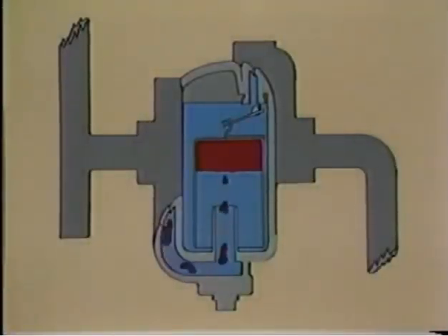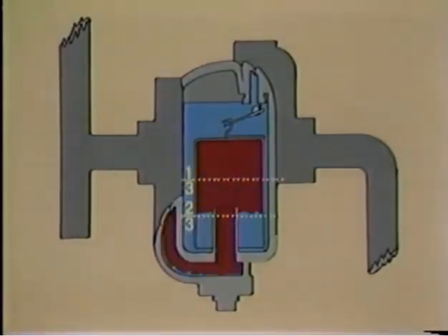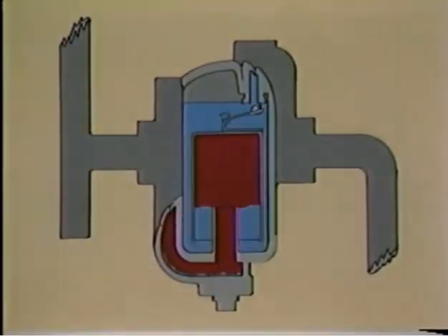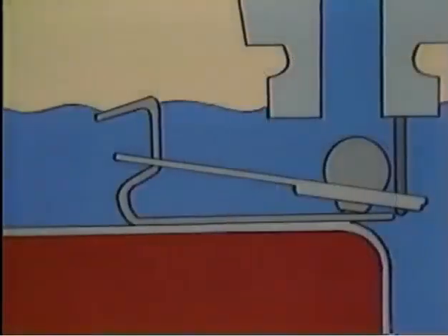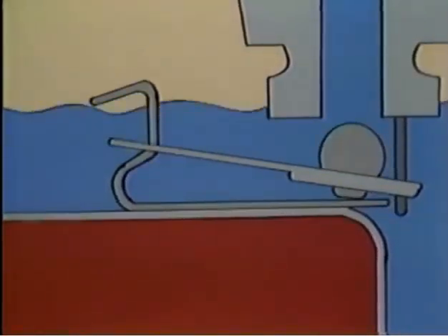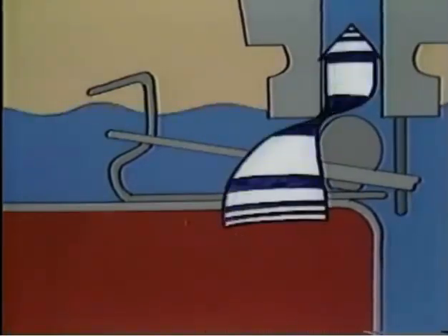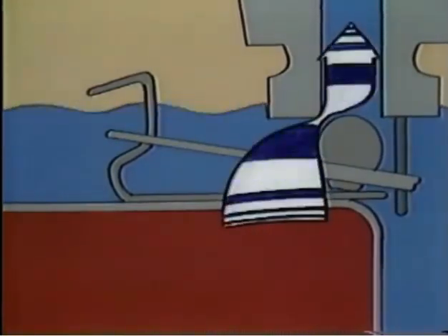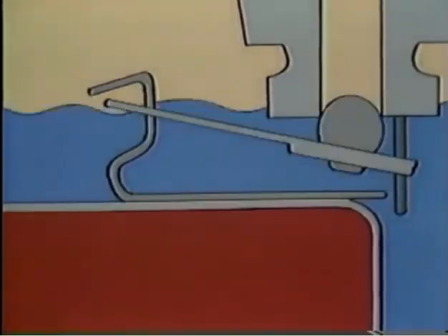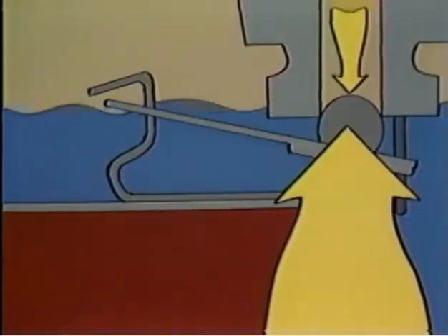Incoming steam is trapped between the top of the bucket and the water seal below. When approximately 2/3 of the volume of the bucket is filled with steam, the bucket becomes buoyant and floats to a point where the valve is pushed toward the orifice by the bucket clip extension. The higher condensate velocity near the orifice propels the valve into the seat, where it is sealed and held shut by differential pressure.